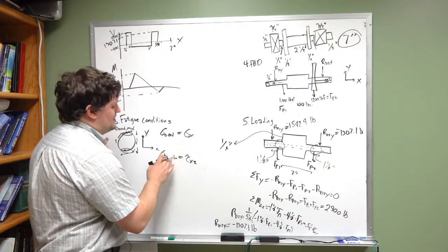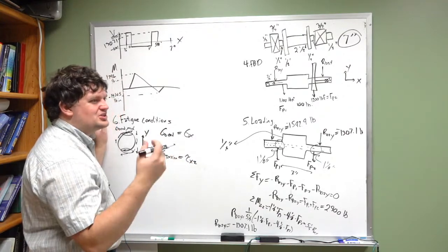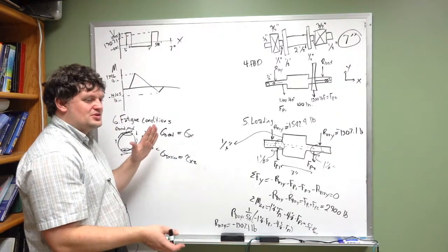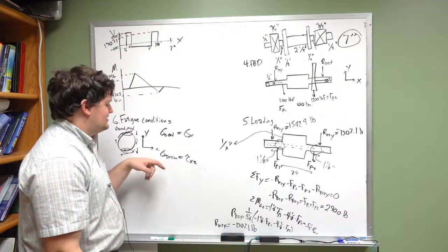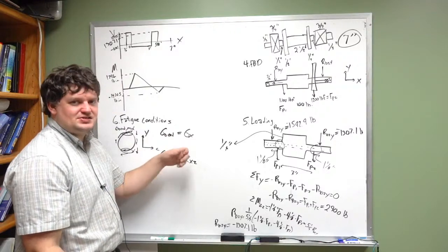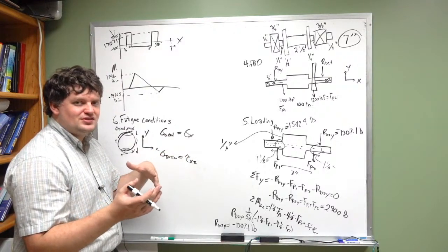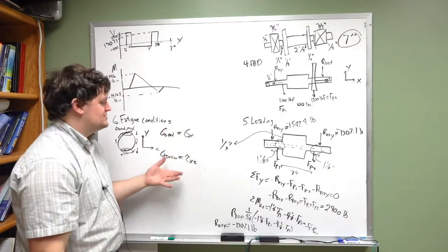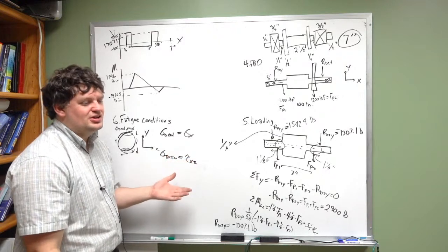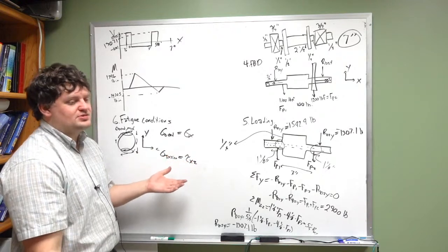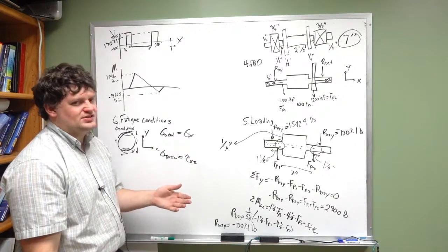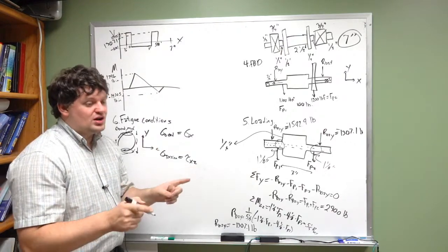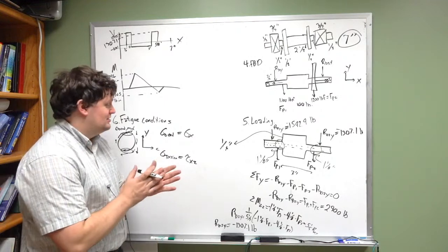It actually technically already is a planar stress condition because you can rotate your axis, and these two shear stresses combine into one shear stress. But I don't like the math there. This math is a lot simpler. Ignoring the shear stress, because it's going to be smaller than the bending stress and the torsion stress, isn't a huge problem at this step because we're not going to be doing this calculation by hand.